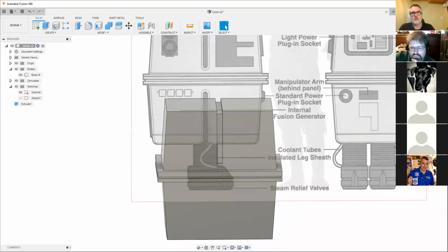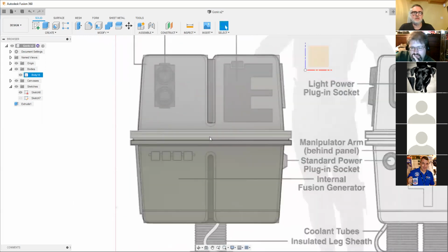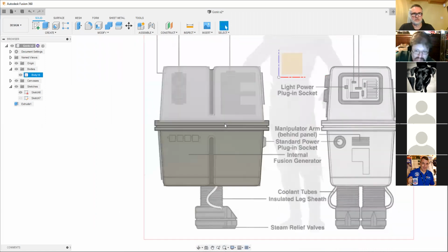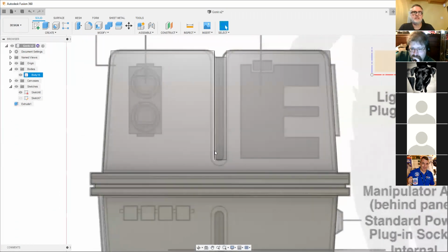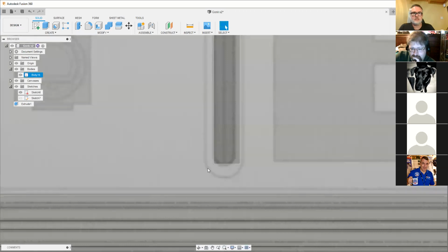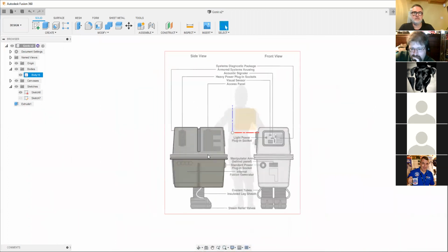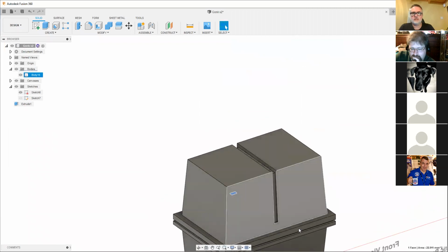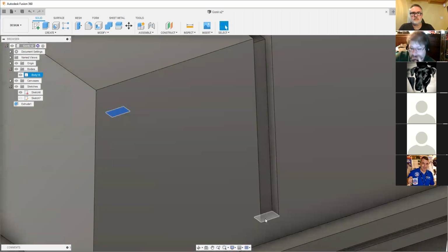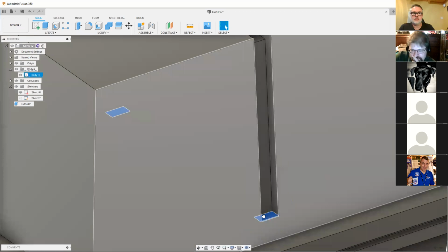And when you start playing around, particularly with direct modeling, I tend to do this quite a bit, which is just combining stuff as we go through. Now, if you combine something and you think, hang on a minute, that actually looks like it should go a little bit lower down to here, what you can do is you can go in and highlight one area. I'm actually going to highlight the two, press pull, and I can now adjust those models, so I can still adjust any of those scales as I've gone through.